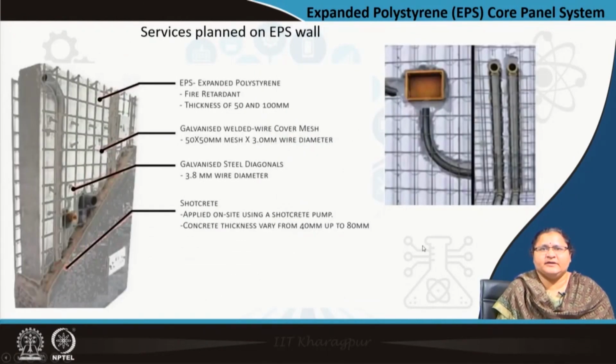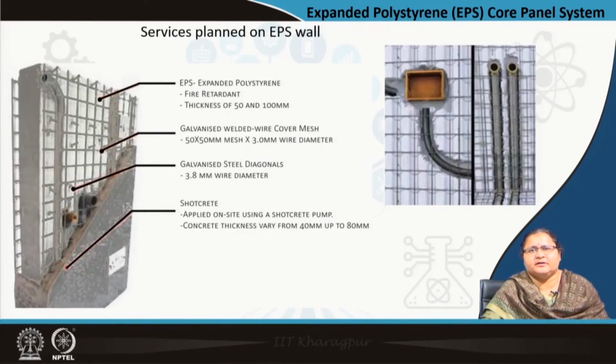When you are planning for all these precast items, you have to remember the service lines. You cannot forget or neglect the service lines. Is it easy to work on top of a precast member? Is it easy to nail? Easy to cut a chase to put your service line? Considering you as architecture students, you may have covered the services part or you may not, but these require a lot of conduits that are to be drawn.